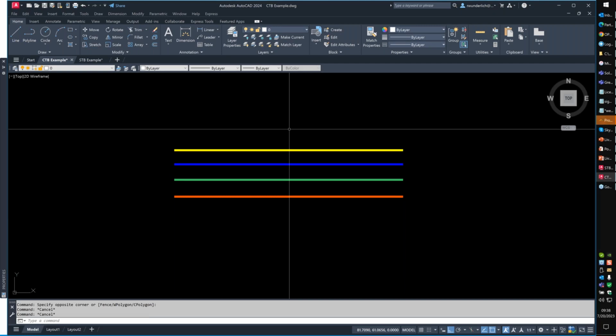You're either missing updates, or you've migrated your settings forward. My previous webinar talked about what to select when, or actually that was my AutoCAD webinar. I think it was my February one. If you can find the link to the February webinar and post it in the chat for me, Lori, I'd appreciate it, where I talked about what to do when migrating settings. If you've migrated your settings forward from an older version, you may have inadvertently migrated the CUI as well, which can cause problems. If you reset your settings back to the default, that should correct that problem, Jimmy.